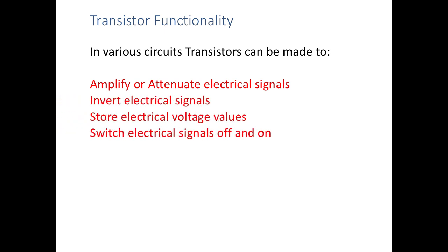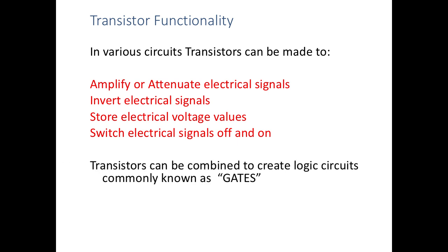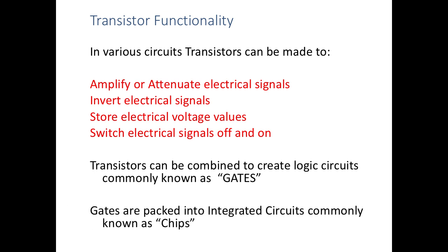The transistor functionality is such that it can be used to amplify, or it can be used to switch signals. Typically, when we're dealing with computers, we're more concerned with having it used in saturation, which is to say, used as a switch. But it is the case that as engineers, we're also interested in using the transistor as an amplifier. And in fact, the transistor can act in funny nonlinear ways, that is, as an amplifier, when it gets loaded down. So we use the transistor to create gates, and once we have the gates, we can essentially fabricate large systems.